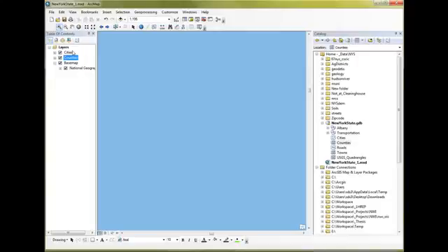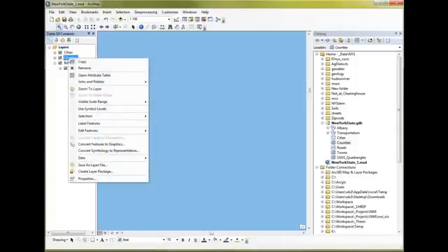The option I'm going to use is within the table of contents and is attached to the layers that are in there. In the table of contents, these are called layers: cities layers, counties layers, base map layers, and they're inside this data frame that's called Layers. If I right click on, say, a layer in here, I will get a context menu. There are many context menus associated with many components of ArcMap. If you really don't know what to do, go to the thing that you want to modify or work with and right click on it and see what happens. There's probably a context menu there.